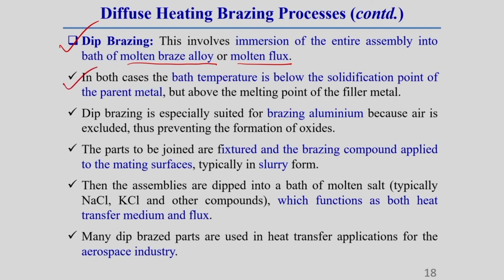In both cases the bath temperature is below the melting point of the base material, or parent material, but the molten bath temperature should be above the filler material melting temperature.